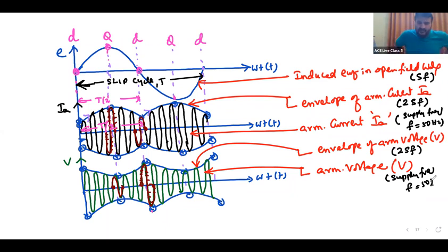Okay. This is about the slip test. And the questions will be again of some type. What are the types of question? You may be given ammeter and voltmeter readings, minimum reading, maximum reading. The previous ESC 2005 and 2008 examinations have given slip test results: V minimum, V maximum, IA minimum, IA maximum. What is XD? What is XQ? That we know. XD is equal to maximum voltage by minimum current. XQ is equal to minimum voltage by maximum current. Right?